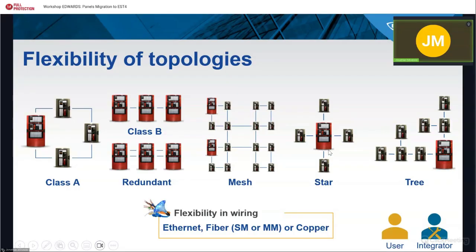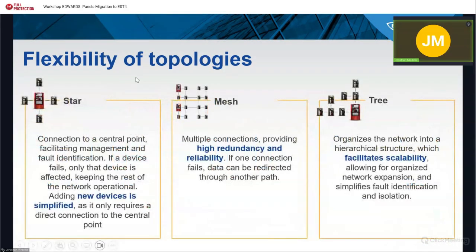So if you're going to migrate, for example, if you have a project with EST3 panels and you want to migrate to EST4, you can reuse the same cable, and you only have to change the CPU of the EST3 to the EST4. You can reuse the same cable between panels, and you will be able to do other types of topology. So I will explain a little bit more about these topologies.